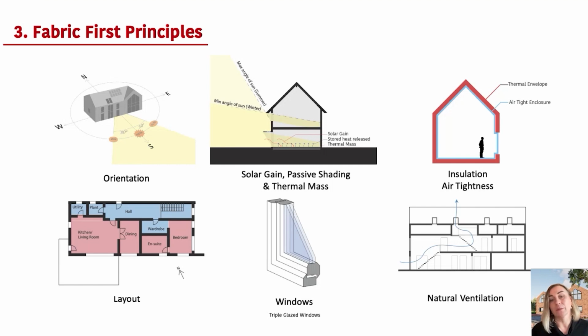So obviously we talked about high insulation levels and potentially a thermal bridge-free construction, and the next one down is the internal layout. When we design the house, we want the main daytime living accommodation, like kitchen, dining and bedrooms, to be located towards the south, and the rest of the accommodation, like plant rooms, utility and hall spaces, towards the north.